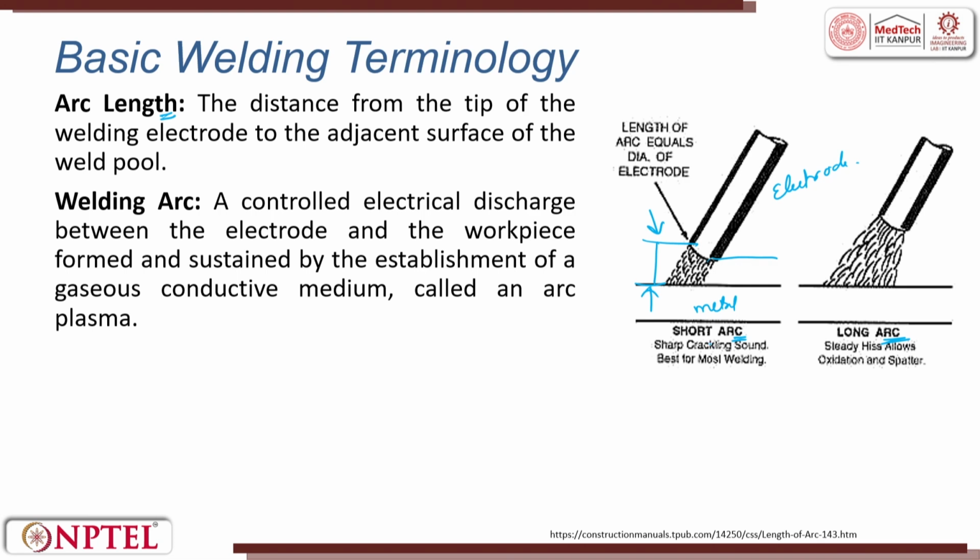When it is short, it creates a sharp cracking sound. It is best for most welding processes with a shorter length. When it is far off, it produces a steady haze, and allows oxidation and spatter to happen or be seen. So, this arc length plays an important role in the power.